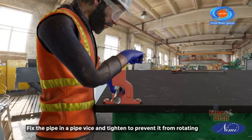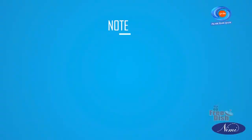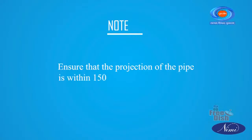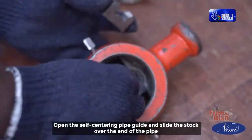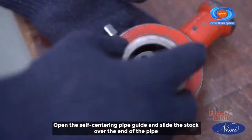Fix the pipe in a pipe vise and tighten to prevent it from rotating. Note: ensure that the projection of the pipe is within 150 to 250 mm from the vise. Open the self-centering pipe guide and slide the stock over the end of the pipe.